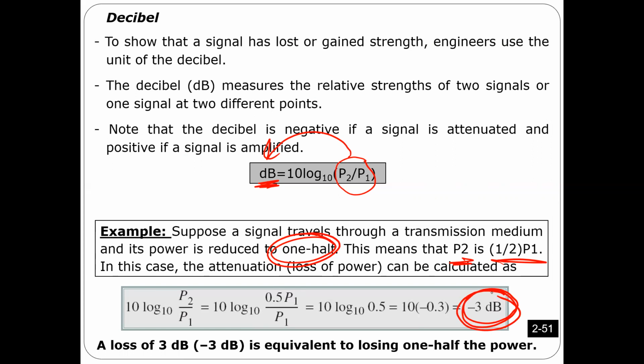Before I take your question, if I say the signal lost half of its energy, it's exactly the same thing as if I say the signal suffered from negative 3 dB. They are just two different ways to express the same thing. You got what I'm saying? So if I say the signal lost 50% of its energy, or I can say the attenuation is negative 3 dB, I'm going to tell you why this is, most of the time, more interesting than a ratio. You have a question?